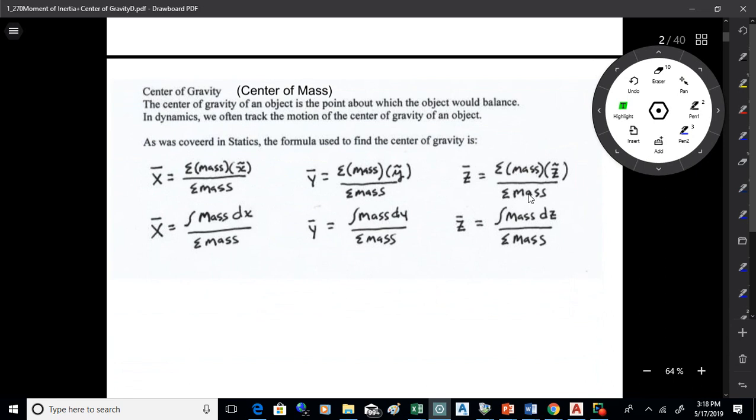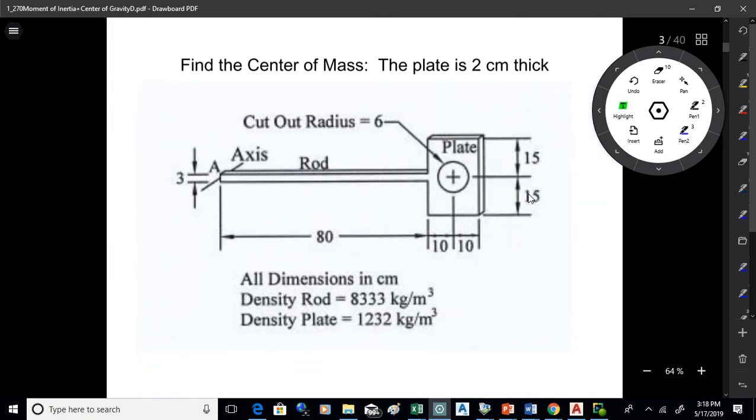All right, so this is a centroid. It comes from the word center, obviously, and we'll use mass to get this figured out. So what we're going to do here is break an object up into pieces, and we might do that with calculus, or we might do it with algebra. And then once we do that, we're going to find the x-bar distance to the center of mass for each piece. We'll multiply those together and then divide by the total mass. And that will tell us where what we call the center of mass is.